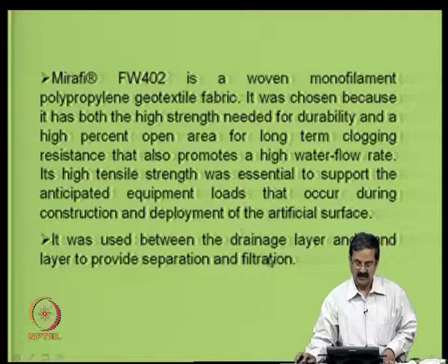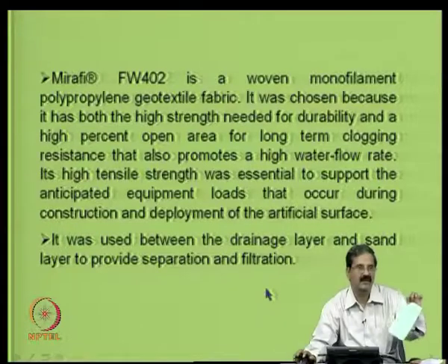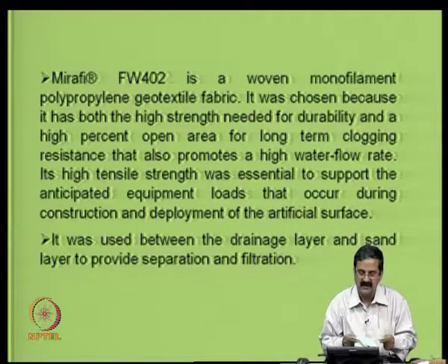So, it was used between the drainage layer and the sand layer to provide separation and filtration. Actually, I must tell you that any of these materials serve both separation and filtration functions simultaneously, because this is a different layer you are just putting as an interface. It serves both separation and filtration simultaneously. Okay.